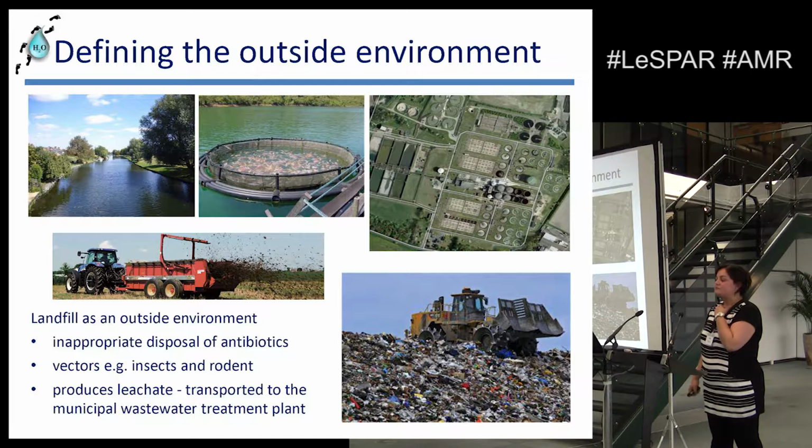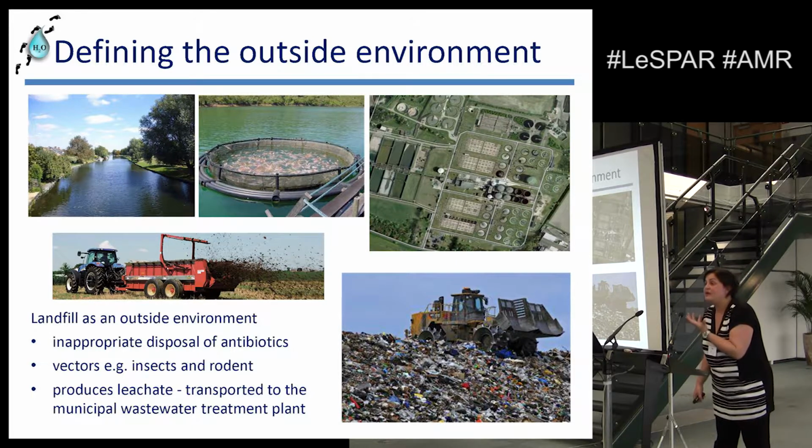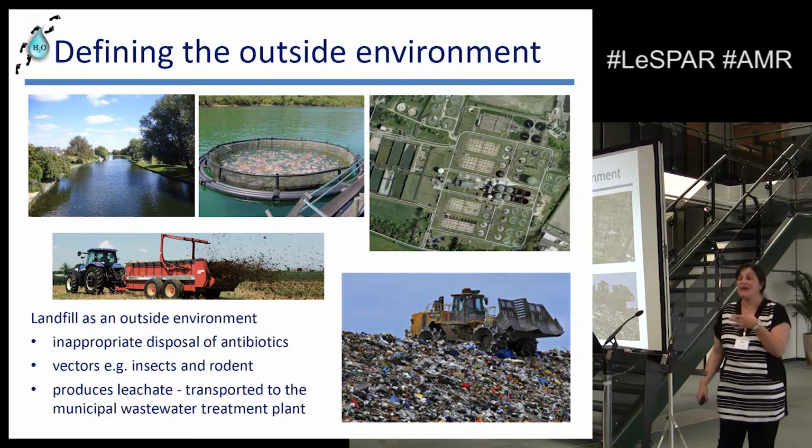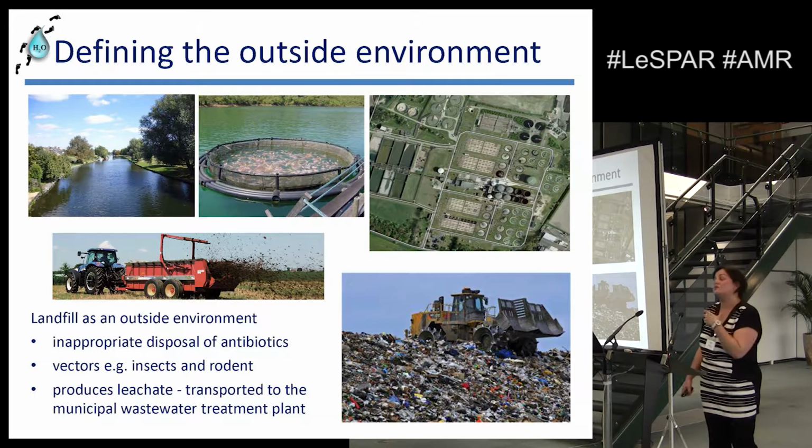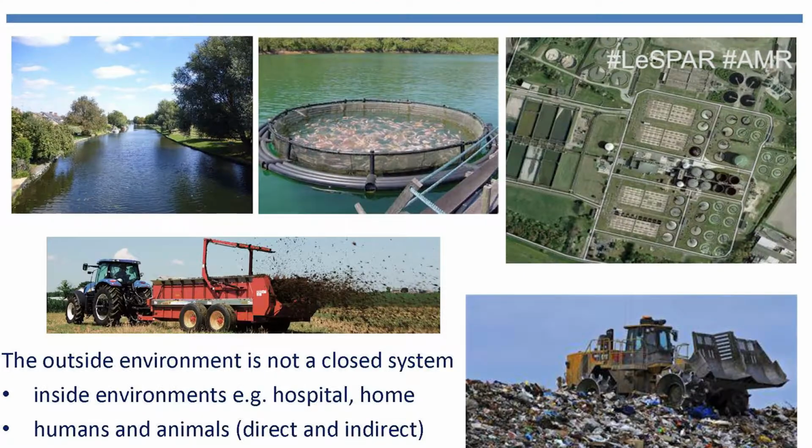Now with landfill, first of all, you've got your vectors, and then you have your collection of leachate, which is basically the landfill wastewater, which will be collected every so often and tankered to a municipal wastewater treatment plant. So it's still entering that wastewater treatment plant, and as a nice, lovely concentrated dose that hasn't gone through the human. So straight away, you have routes by which antibiotics enter a system, and it's not just the antibiotics, but also the antibiotic resistant bacteria or genes, whether they're already there or whether they're then being selected.